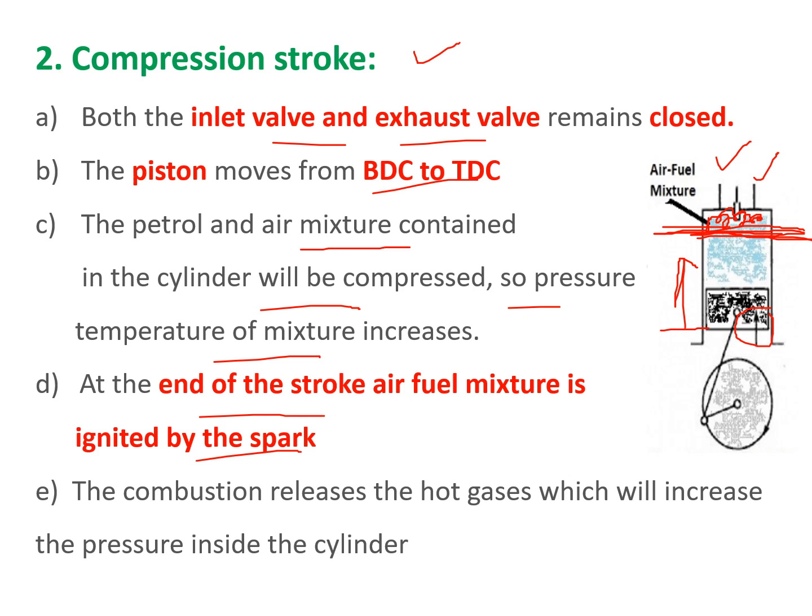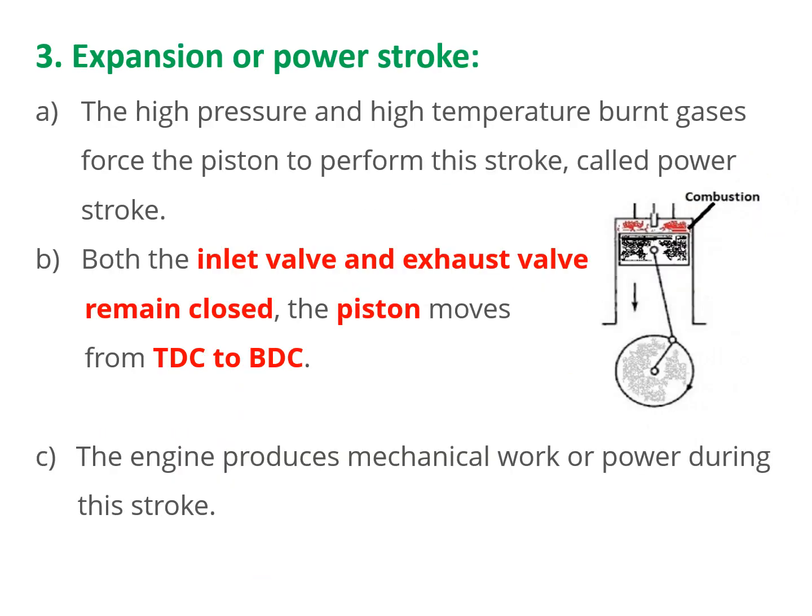Okay, so by the initiation of the spark, the combustion takes place, which releases the hot gases, which will increase the pressure inside the cylinder. So the combustion is just at the end of the compression stroke. Now the third one, that is the expansion or the power stroke.